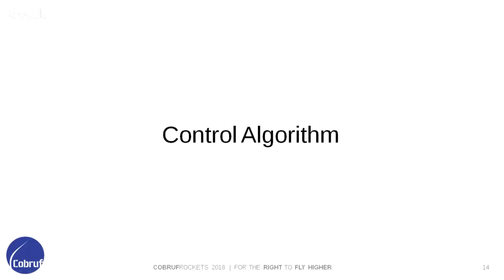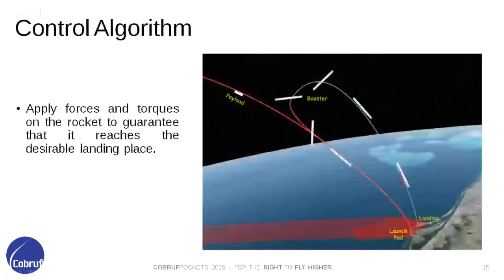I'm going to talk a little about the control we assessed in this study. When you think about the traditional control law, we have to know the desirable path which the rocket must follow. Within this approach, the error is calculated by finding the difference between the actual and desired position in space. But once the rocket has already taken a wrong path due to external disturbance, getting back to the desired path demands energy. Instead of expending energy to get back onto the original path, the idea was to investigate a strategy which calculates the error between the desired landing place and the predicted landing place.